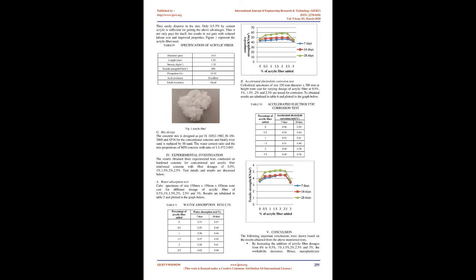Application of acrylic fiber reinforced concrete used in construction. The thinner and stronger elements spread across the entire section, when used in low dosage, arrest cracking and increase flexural strength. Acrylic prevents the shrinkage cracks developed during curing, making the component inherently stronger. Further, when the loads imposed on concrete approach that for failure, cracks will propagate, sometimes rapidly. Addition of acrylic in concrete prevents or arrests cracking caused by volume change, expansion and contraction.